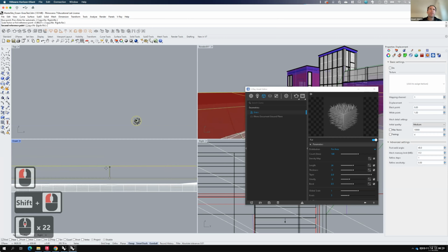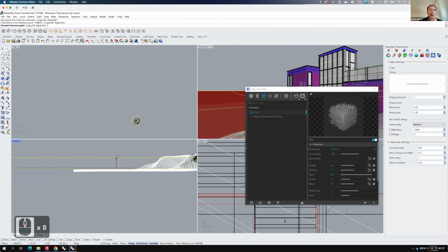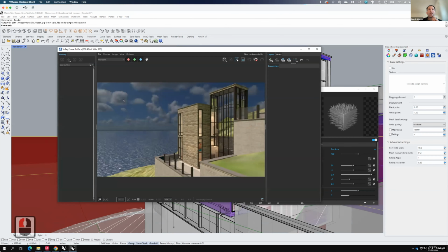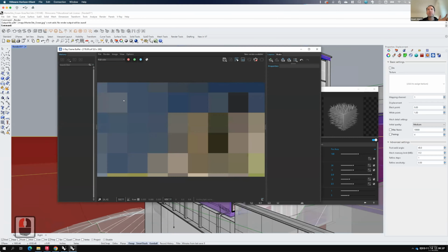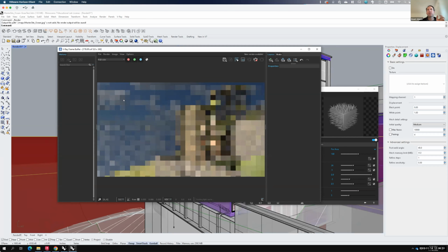So I'm effectively raising the horizon, and you can see it over in this view when it happens. I can raise up that horizon so it's past where that little bit of the HDRI was showing, and then we can re-render this one. The daytime render is actually the most challenging render to get really good results because of the ground and the surrounding context. That's always the hard one.